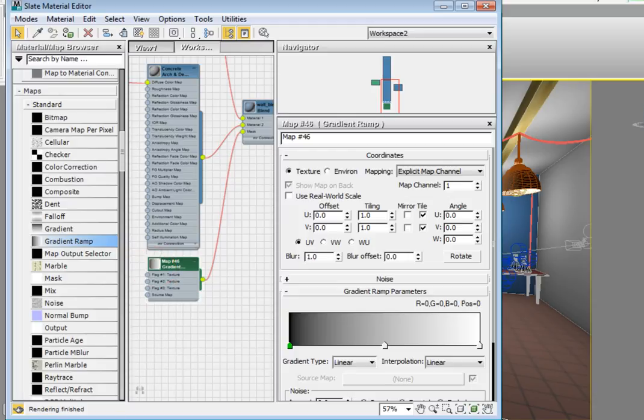In order to change this, navigate to the coordinates rollout for the gradient ramp, locate the W option for the angle, and type in -90. Then press Enter to accept the value. If you now look in the sample window for the map gradient, it's now oriented vertically from top to bottom. The only thing you should see at this point is the change in the preview of the map in the map node. The gradient we see in the Attributes Editor is for editing only.